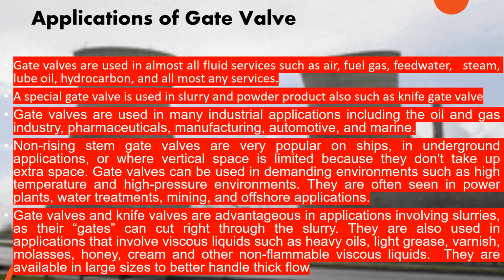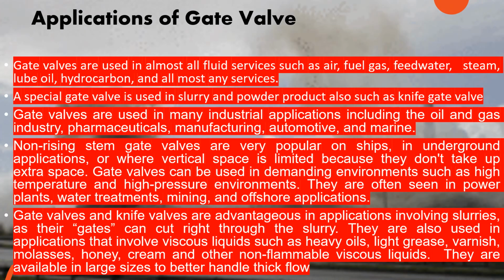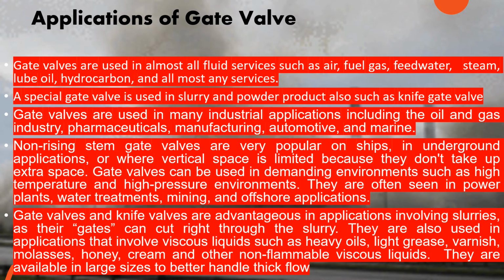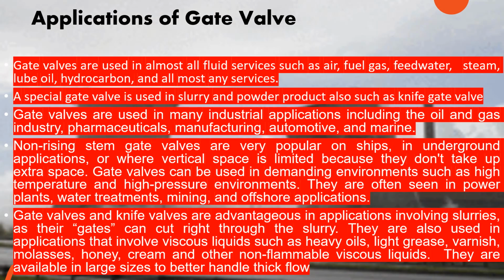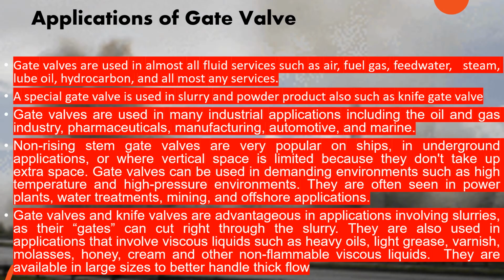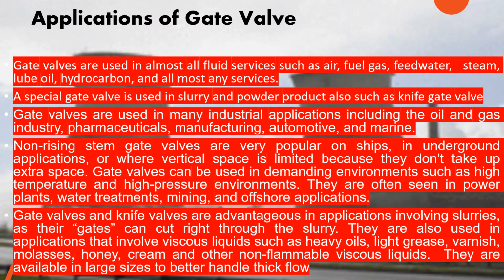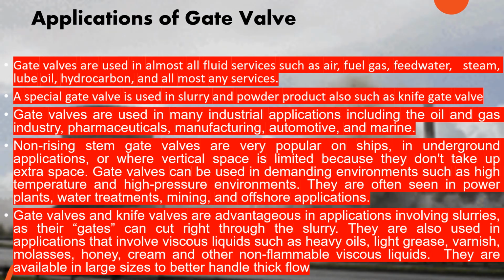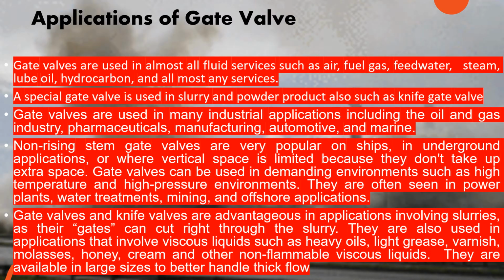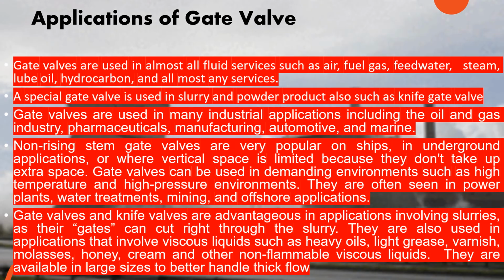Gate valves are also used in applications with very thick fluids: liquids, slurries, heavy oils, light grease, varnishes, molasses. So for any highly thick or highly viscous liquid, we can use gate valves, and the condition is mostly that it is a non-flammable fluid.